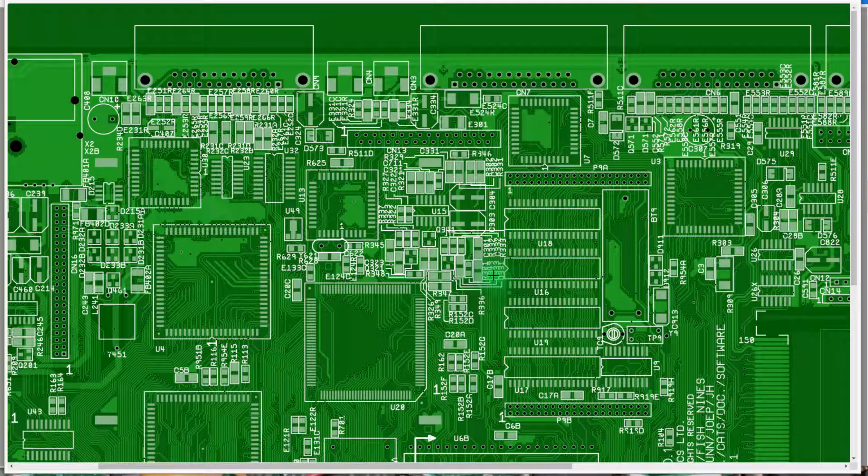Have I got anything else to say here about this in this first video? I don't think so. I think we talked to the fact that there's various discrete components, resistors, and ferrite beads and things in the audio chain here. I haven't specifically called those out. If, when I go through the high level, I find a spot where the signal stops, I'll come back and identify the components in the chain and probably actually draw in red leads that show the signal flow. And then I'll come back and do some more in-depth probing.